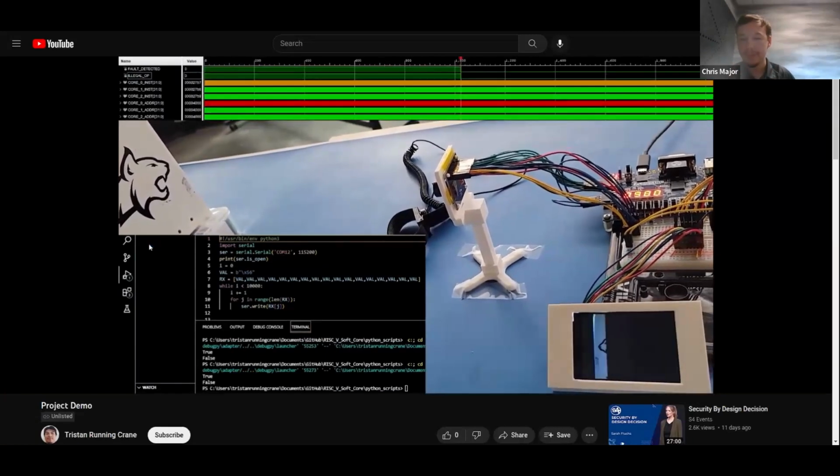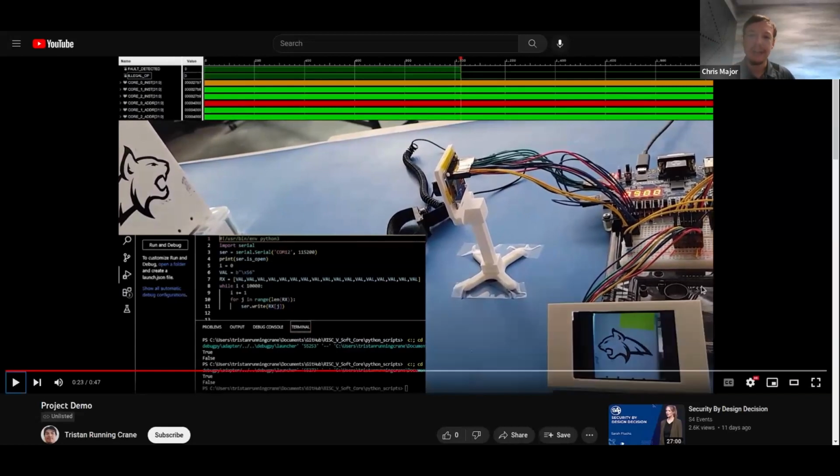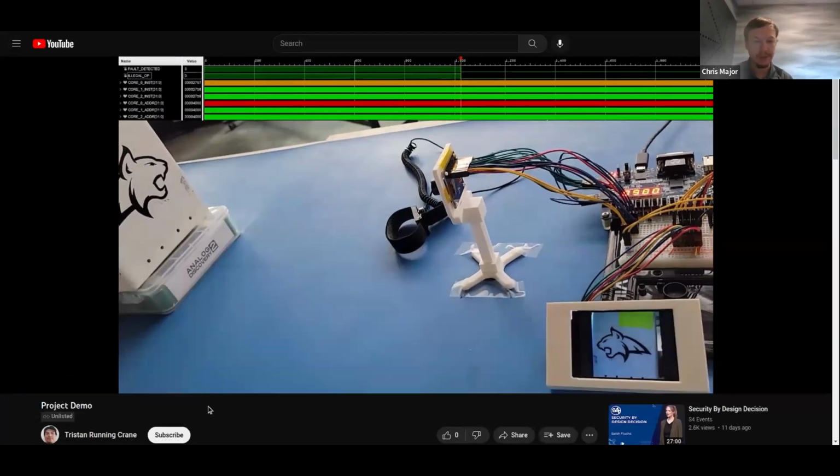There we go. So the image has come back online. And as you'll notice now, our recovery mechanism went back through the program memory and cycled out the bad opcodes for a copy of the known opcodes. Now this copy in the recovery mechanism cannot be read by the processors and cannot be attacked by the attack vector. It's completely quarantined from the rest of the system. And because we're able to bring back in those opcodes, we refresh the entire system with good program memory once again, and we let it continue out of reset. And so as you can see, we're gathering live data again. There we go.